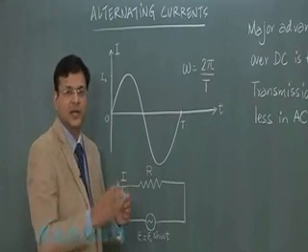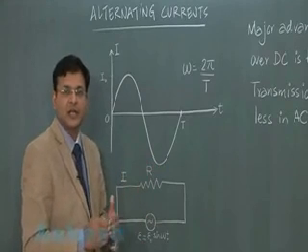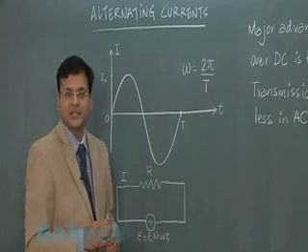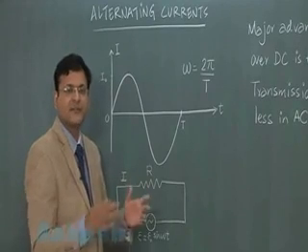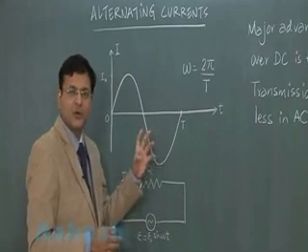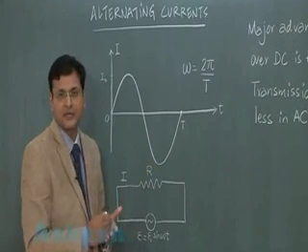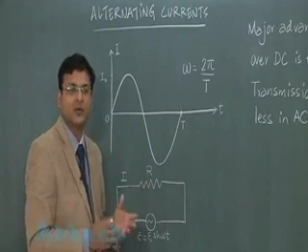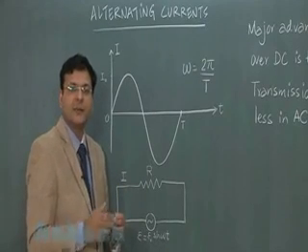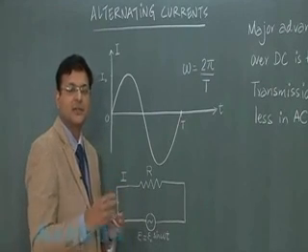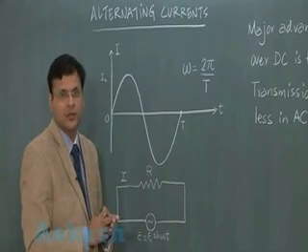You understand? If you look at any circuit diagram related to current, our main purpose is to know how much charge this current is flowing in that circuit, and how much heat this current is generating in that circuit. So whenever you are interested in knowing about a quantity which is related to charge flow, then we talk about average value of current. And whenever you are interested in knowing the amount of heat it is generating in a particular circuit, then we are concerned with the RMS value, or you have already known this term, root mean square value of the alternating current.